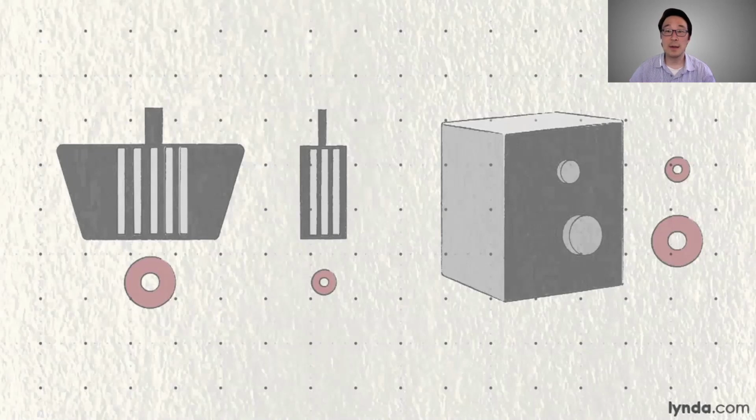Similarly, on, let's say, big industrial machines, usually the on button, on the right here, is really small, whereas the off or stop button is usually really big because you want to be sure somebody really wants to start a big piece of machinery, and then if you want to stop it, you want to make that very easy to do so that people can hit that target.